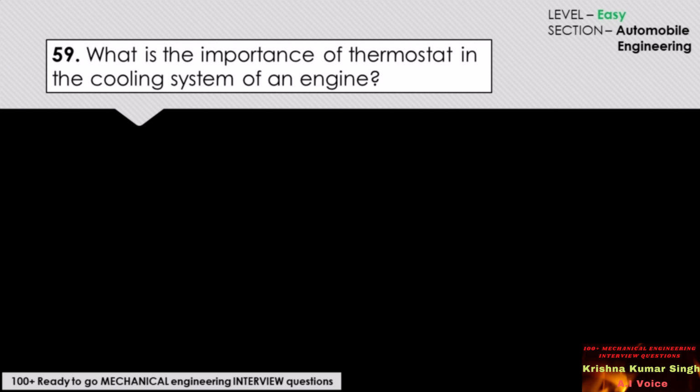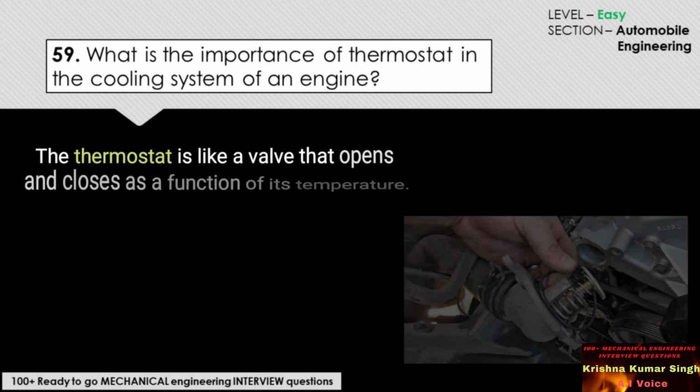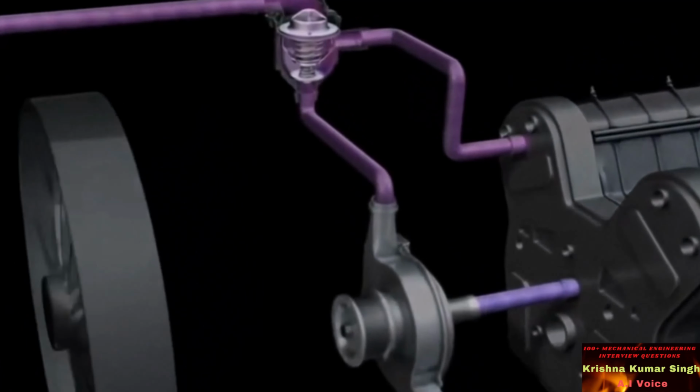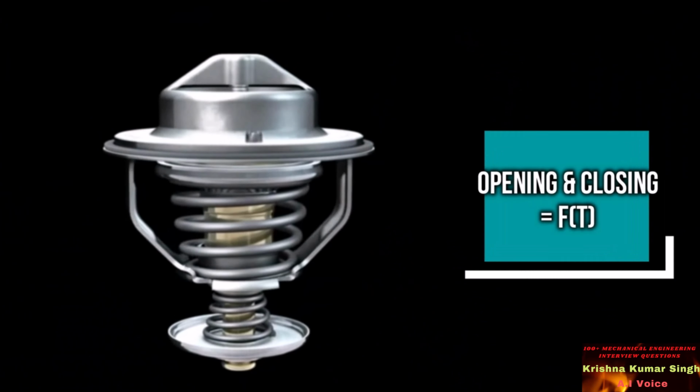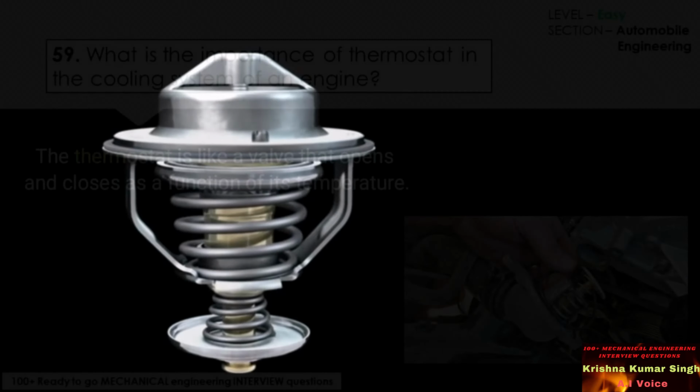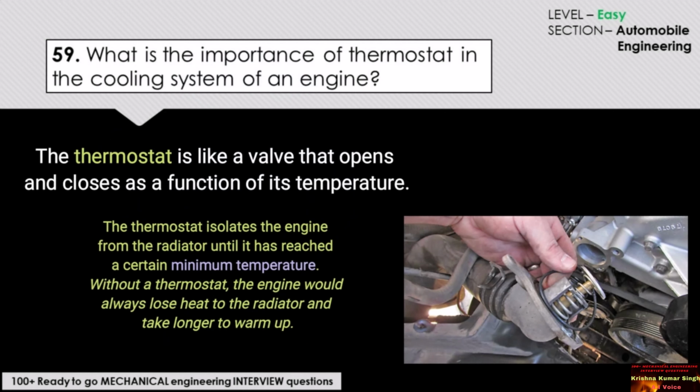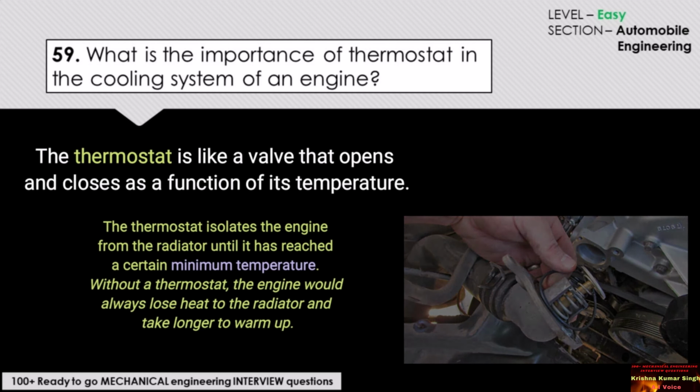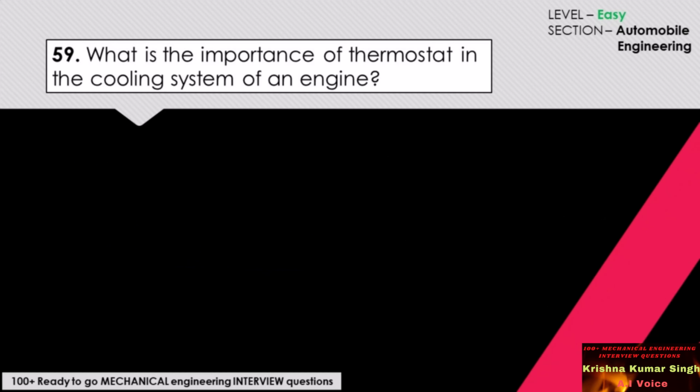What is the importance of thermostat in the cooling system of an engine? The thermostat is like a valve that opens and closes as a function of its temperature. The thermostat isolates the engine from the radiator until it has reached a certain minimum temperature. Without a thermostat, the engine would always lose heat to the radiator and take longer time to warm up.